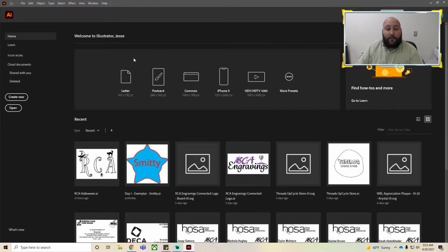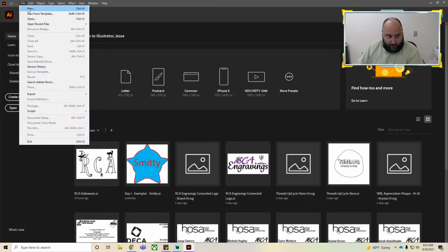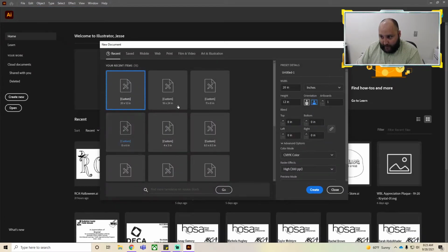All right, so the first thing I want to do, all of you should pull up your Adobe Illustrator now. It should be up. Pause me if not. So every time we work with the GlowForge, we're going to need to create a new file. So you're going to go to File, New, and it's going to pop up here. I've already got mine created.